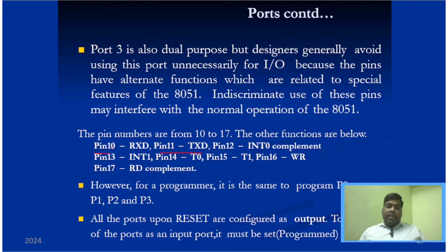So pin 10 and pin 11 are used in serial ports, that is TXD and RXD. Similarly, pin 13 is interrupt 1, and pin 12 is used for interrupt 0, and similarly pin 14 and pin 15 for timer 0 and timer 1, and pin 16 and pin 17 for read and write operations, right? So these are the different functions of port 3. So designers most probably will not prefer port 3 for input output. They will prefer it only for special functions, right?